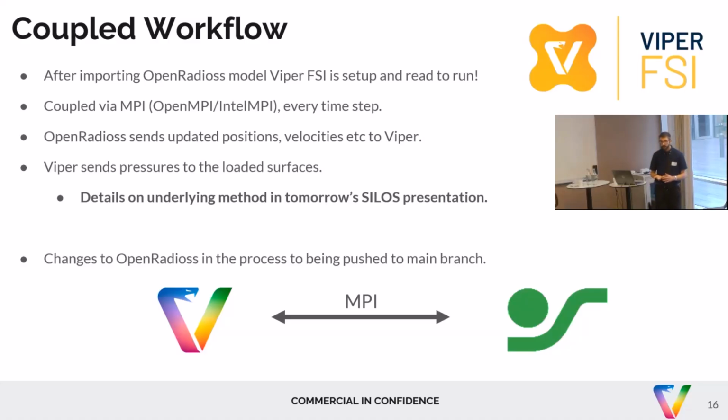So we use OpenMPI, but we've also been doing a lot of testing and further performance enhancements and development on Windows, where it runs with Intel MPI. We are passing information back and forth on every single step. So we always have to pick the minimum time step between the two, and are always evolving on that time step. So the fluid and the structural response are perfectly synchronized.